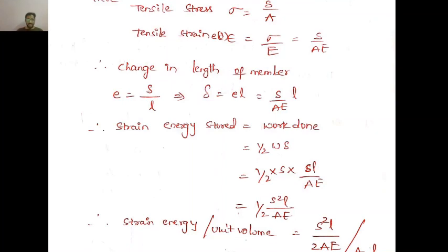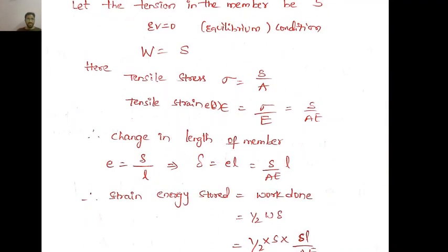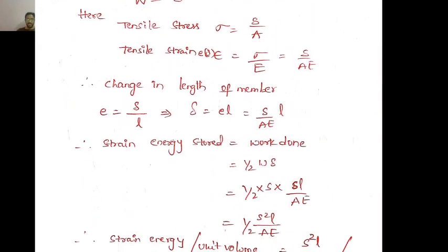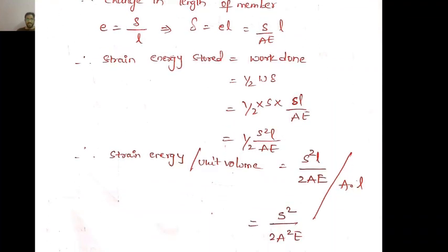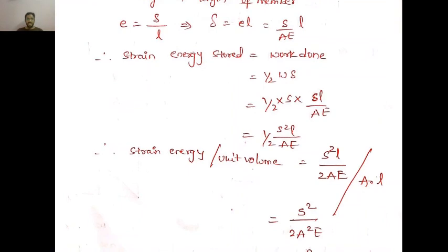From the equilibrium condition, load is equal to tensile force, and change in length delta is S L by AE, so finally we got S square L by 2AE.